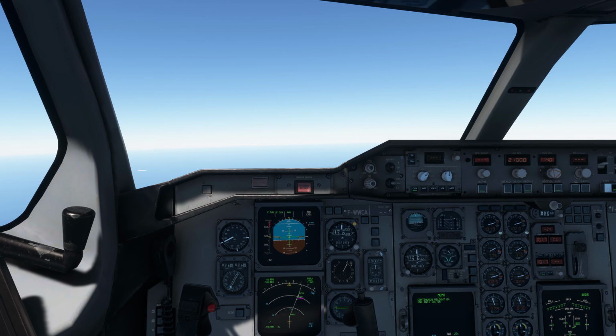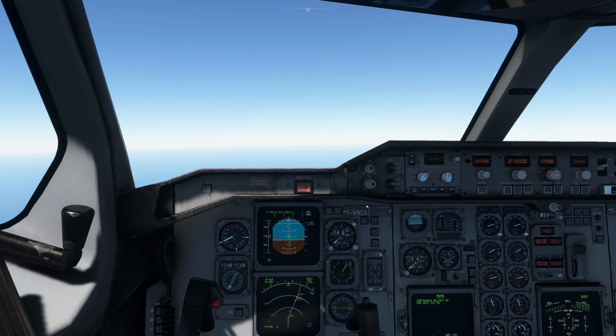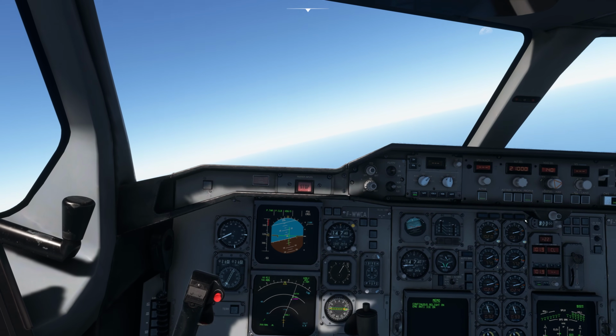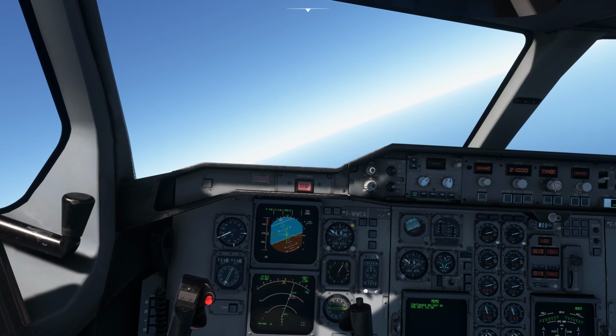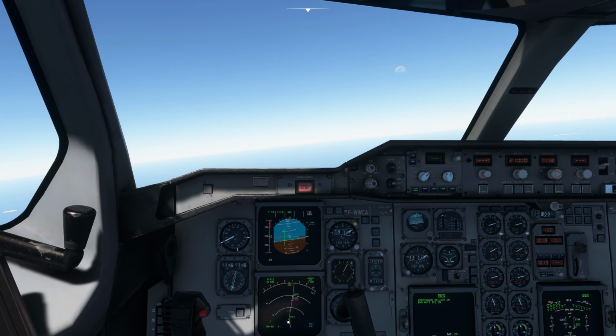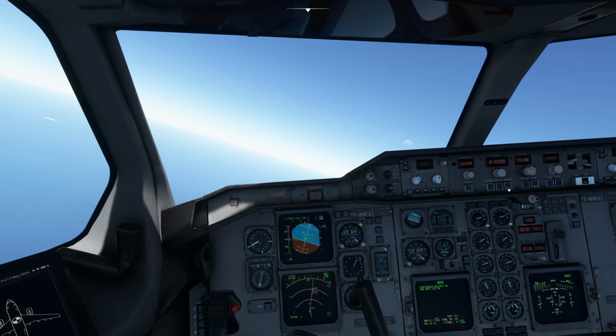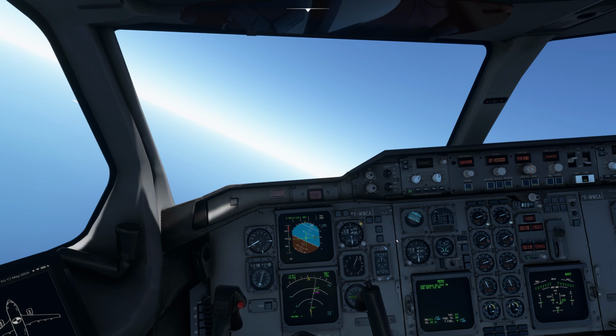Then there is an open mode. If you bring the plane in the flight level change mode or in the vertical speed mode, then it will be an open climb or open descent, and then this profile mode will just go away, and then you can see nav is coming, which means the plane is in the nav mode. And if I just move it to the heading mode, you will see heading select mode is coming, and now the plane has started to turn towards the right side because it will follow the heading, and whatever heading I select over here, the plane will actually follow that heading. So let's press this nav button again, and then you will see nav coming. It means the plane is following the flight path. So if you deviate from the flight path anytime, you can press the nav button, and the plane will actually start to follow the nav mode.